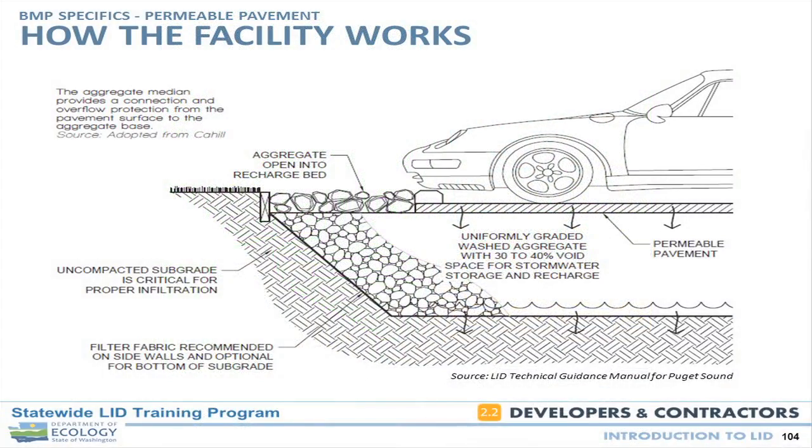I know this graphic is in the manual, how it works. You can see there we've got our wearing surface of whatever type on top, and then we've got our reservoir course, which we mentioned, the gravel, open graded large chip rock over here is for storage of water and also supports the pavement, but as a high void content, provides storage for our pavement to infiltrate.